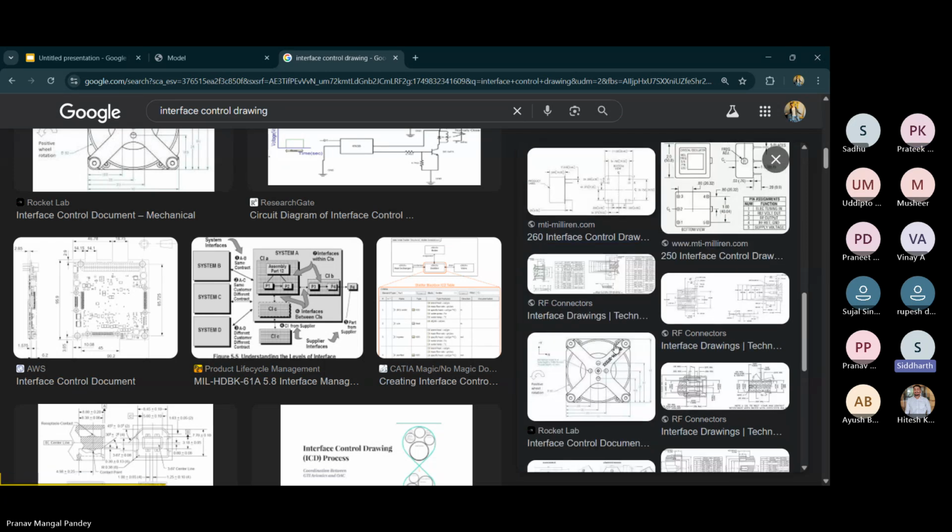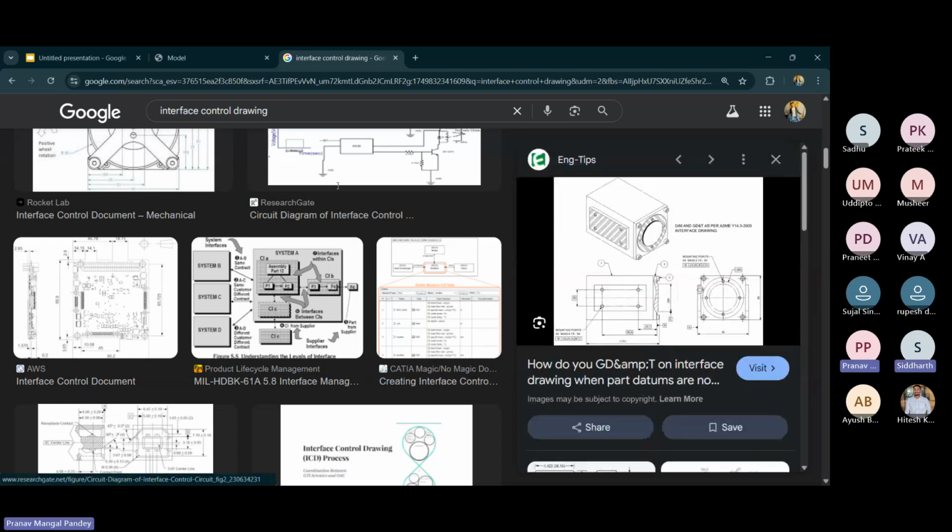Okay, so what is an assembly drawing? It is more like the complete system shown in one drawing. For example, let's say you have a nail cutter. If you make an exploded view of the nail cutter, including its main body, the two or three types of blade inside it, and the pins connecting it with the upper handle, and all those things are shown in a single design, then it is an assembly drawing of the whole nail cutter.